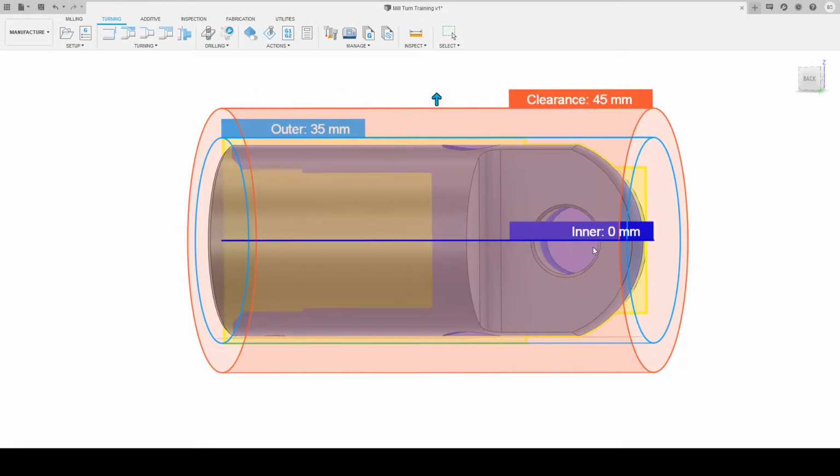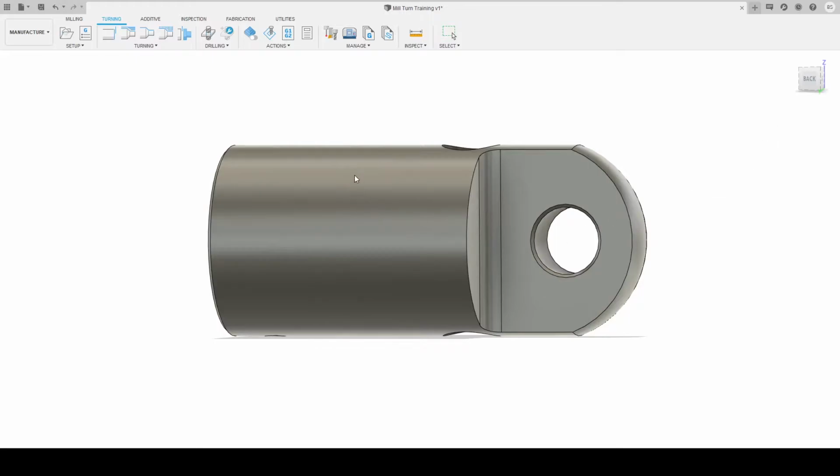And that takes us back to 0. Okay, passes. This is where we set our maximum depth of cut. If we want to go vertical passes, back cutting, horizontal passes, the direction, if we want to allow grooving, if we want to use a canned cycle, passes, we can do maximum depth of cut, so we can go about 2 millimeters pretty safely on this.